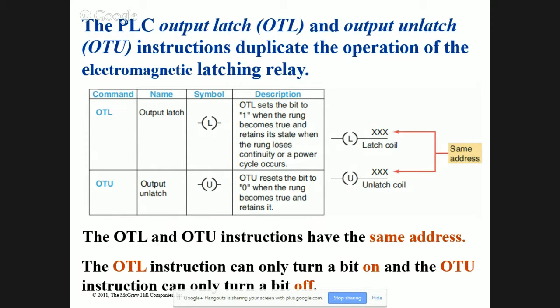However, if you do that, especially for motor control, what you'll find is either you screwed up or somebody else screwed up, and you've got this motor latching and unlatching 100 times. You tell it to come on one time, and you're not paying attention to the logic that's 30 rungs below, and then something happens and it turns it off, and you can't figure it out. So if you don't use these for motor control, you just use a seal-in circuit, as in our previous example, then you'll know where to look if the motor's not coming on or going off too soon.